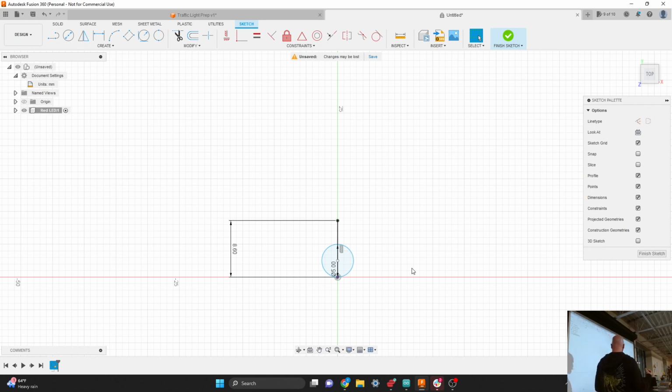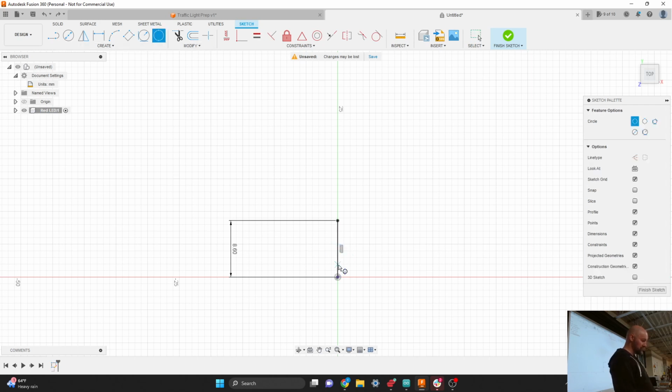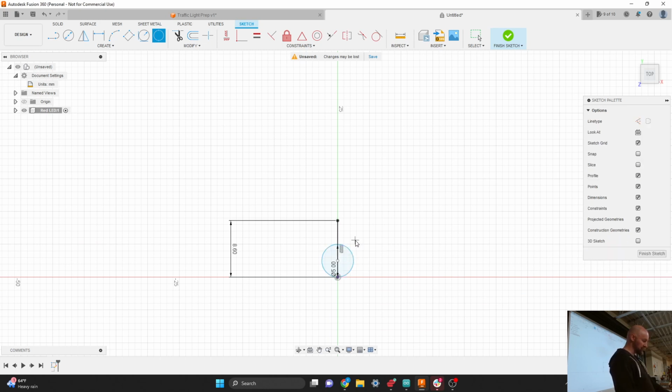A blue sketch is normally a sketch that represents something that is not fully constrained, right? So in theory this blue sketch is not fully constrained, but it definitely is, because I can't click and move it anywhere. And it seems like, oh, I can click and move it. Look at that. I must not have clicked right the second time. So I'll click that first one, 5 millimeters, and I'll click on the line the second time.